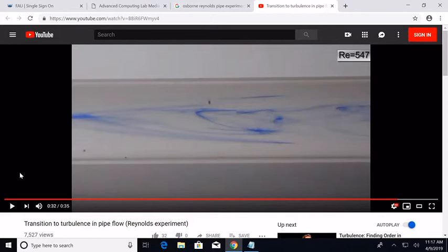Can you explain, give us a few examples? If you are adding any solvent that you actually need to be concentrated at a uniform rate in a fluid, then turbulence is good for you. Like if you're adding something into the water in the pipe flow, which has to be uniformly distributed in the water, then mixing is good for you. For example, what would you want to mix evenly?